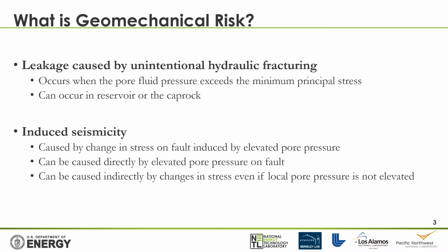And the other is induced seismicity, which is a little bit, well, a lot harder to predict, but stress, we believe, plays a role in it. And so this is caused by changes in stress on a fault induced by elevated pore pressure, or can be caused remotely, indirectly, by changes in stress, even where the local pore pressure is not elevated.